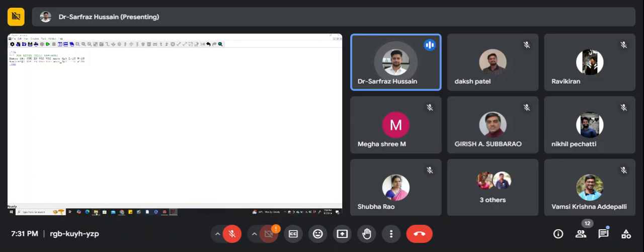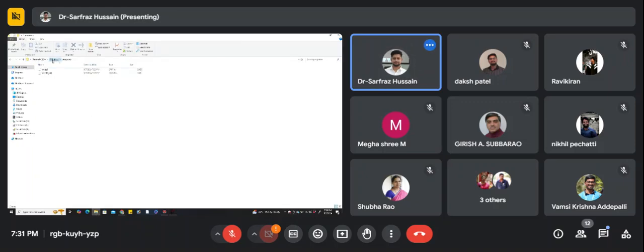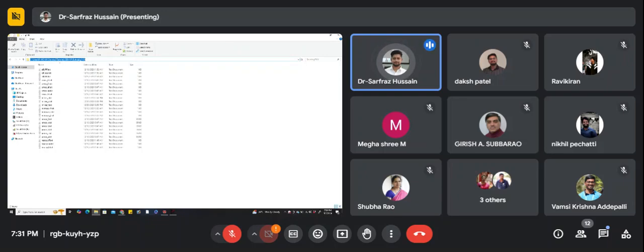Now here, if you see the location of this particular file, or you can say the technology, this is the GF180 nanometer technology, right? So we can select this whole location, or you can select just .gf180. Directly also you can call upon this one. Whatever name we are talking about, let's say for example for NMOS and PMOS typical, we can call upon this CMOS underscore TT.